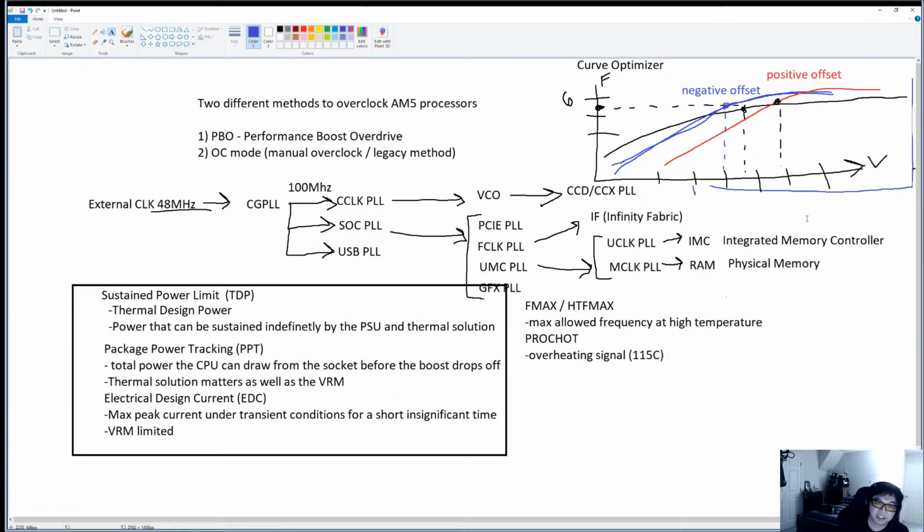You had to go through, yeah. See, and that's the binning process. So this is something that I think is definitely worth looking into. If people watching this video have the Ryzen 7000 CPUs, you can play around with this. Just know that your mileage may vary. So there is going to be a lot of trial and error. You might be able to set it to -30 and it runs fine, but then you put it to sleep and you wake it up and then it's unstable after it comes back. Those sort of things. I've seen that happen, or I've heard reports of that happening. So you might have to back it down to -15.